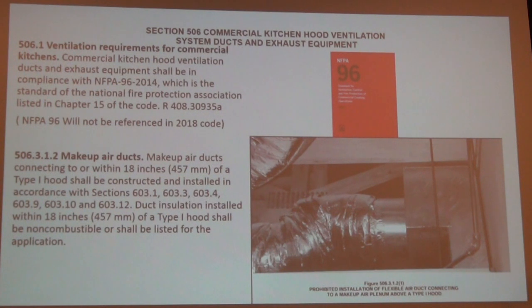I used to see a lot of them, but not anymore. Most of them now, the makeup air comes out of the front of the hood, or it's actually separate ducts. So I don't see any more makeup air coming right into the plenum of the hood plume.